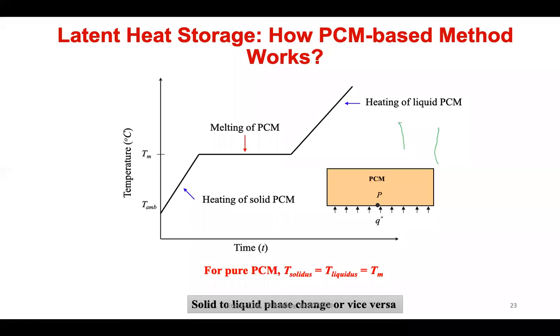Now what will happen? The temperature of the material will go up, and it will reach its melting temperature, and once the melting is completed, the temperature will rise again. During melting there is some latent heat of fusion, which we want to utilize here. I have cited the example of paraffin, but you can see it for water also. Water changes from solid to liquid, meaning ice, and again liquid to vapor, where we get boiling. Each stage has some latent heat, and we are targeting that.